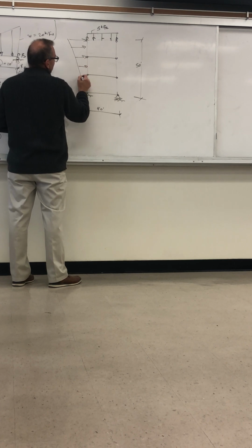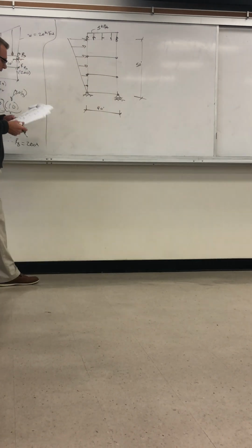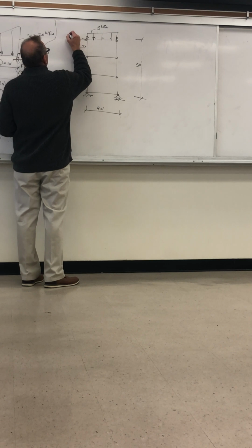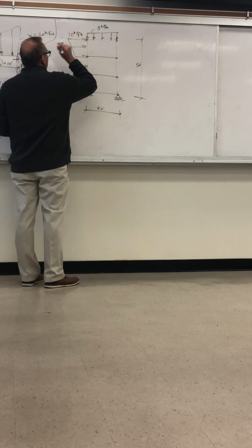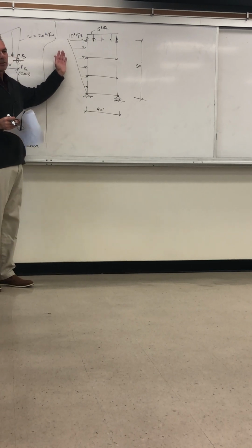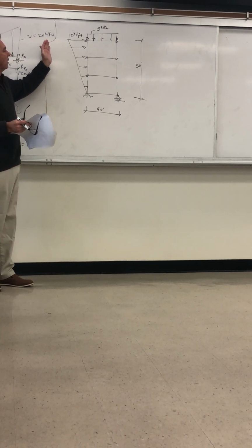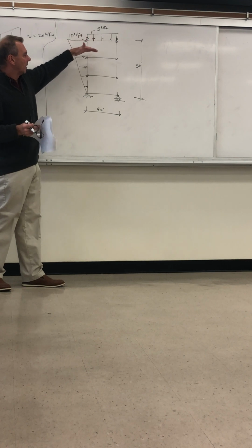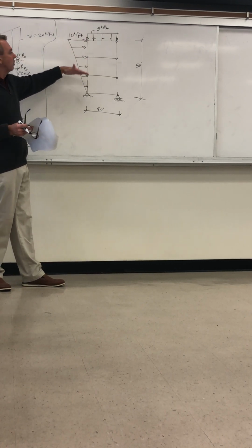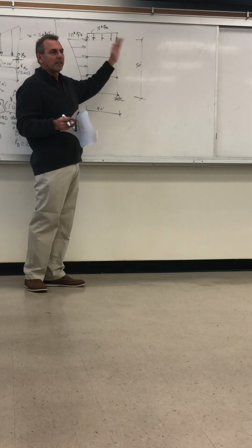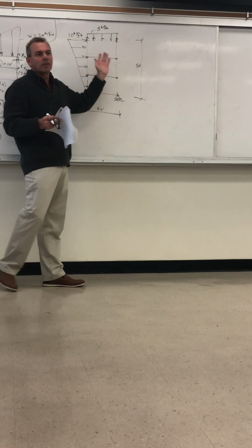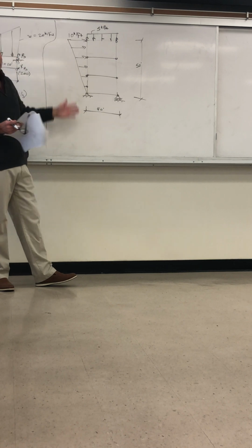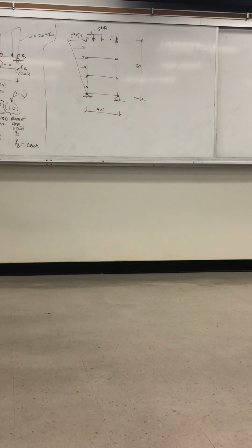And this is consistent with it could be wind loading, lateral loading, or earthquake loading. Earthquake loading is inverse triangular like this typically, or at least approximately. The reason it would be inverse triangular in earthquake loading is the force that any part feels is the mass times acceleration. Let's say each floor has a constant mass distribution, a weight distribution, and the structure under earthquake loading displaces approximately like this linear increase. So your accelerations would be larger at the higher part of the structure than the lower. So you end up seeing a distributed load from earthquake loading that looks something like this, inverse triangle.